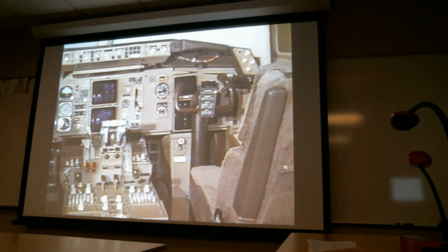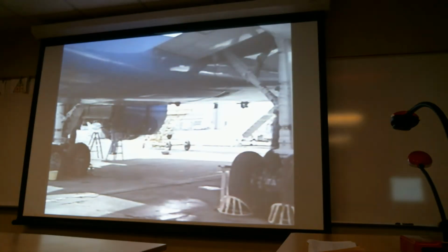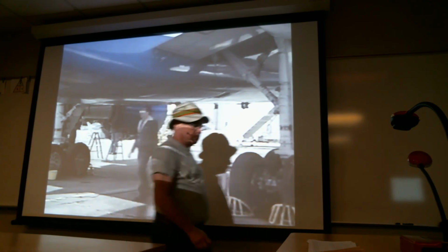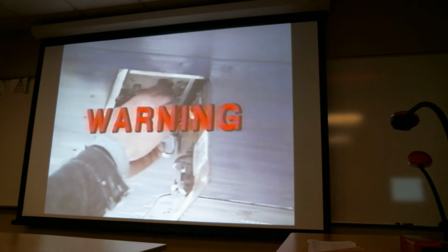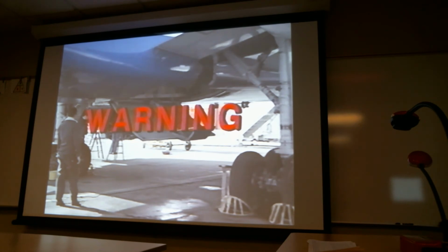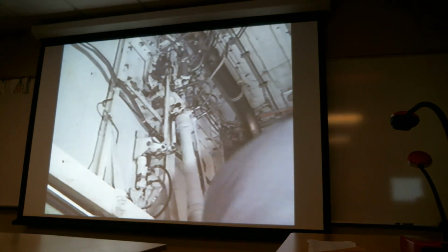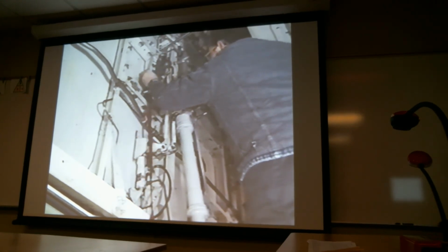After maintenance, a flight deck check of the hydraulic system has indicated an overfull condition on the right hydraulic system. This condition requires that hydraulic fluid be drained from the right system reservoir located in the right wheel well. To gain access to the right system reservoir, the wheel well doors will have to be opened. Warning: rapid action of doors may injure personnel or damage equipment if locks are not properly installed. Next, install the door safety pins.